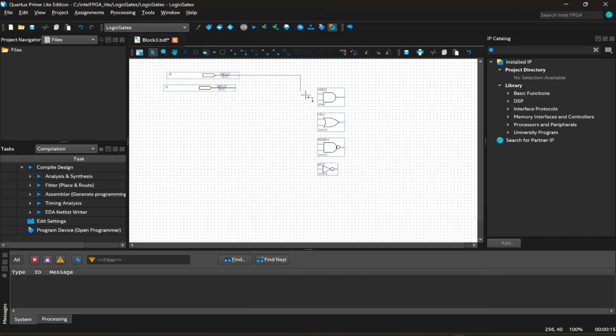Okay. So now we can connect them directly. We can connect this to this input, but I'm going to do it another way. So now this is directly connected to this input. We can do the same thing for B and then branch it and connect it to all of the other gates. But let me show you the other way. It's better, more efficient, especially when you have big circuit designs. So let's create a branch here. For every input, you can left click and drag.